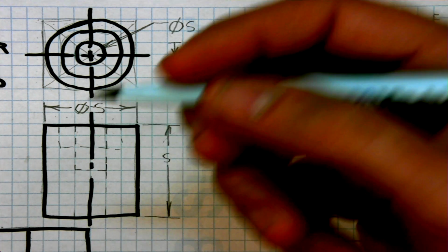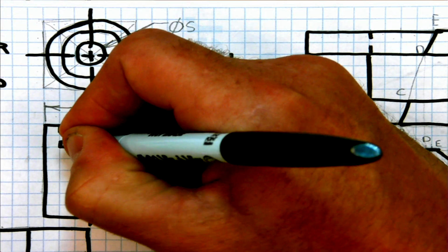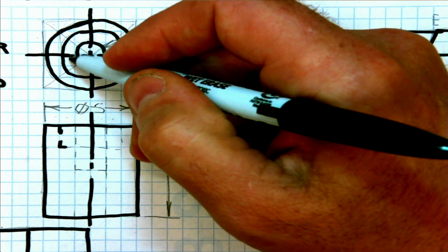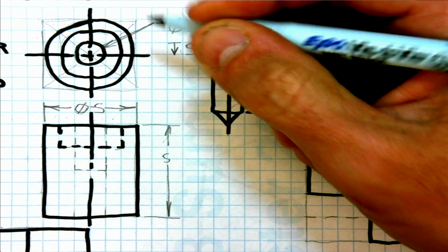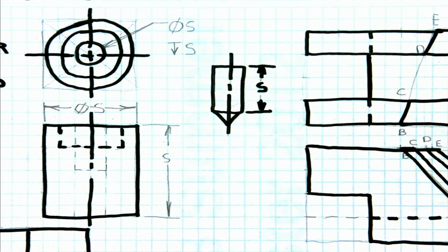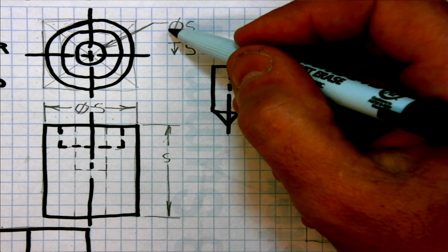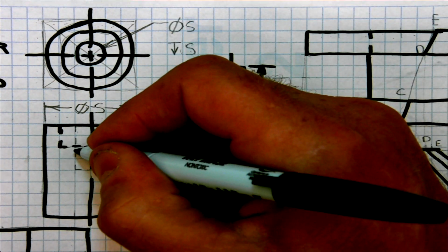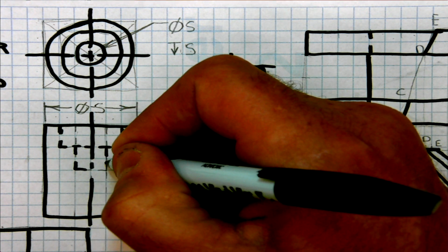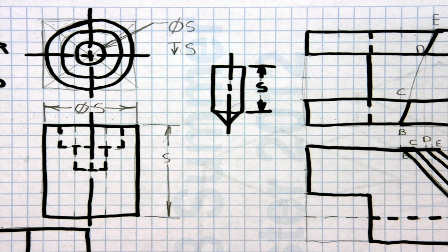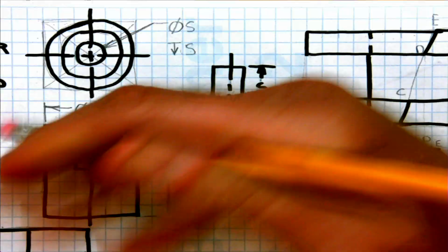Okay, so what we have now is this comes off, this becomes an L shape. And now if we just had this hole right in here, just a counterbore hole, it would go from one side all the way across. You'd still have to show this surface back in here. But now notice this has also got the blind hole in here. So you're saying diameter size, the depth of size here. But now this part of this blind hole has been cut out. That forms a T, that forms an L, a dashed line across there. Now you've actually gone through and made this counterbore hole. Okay, you've made the counterbore hole.